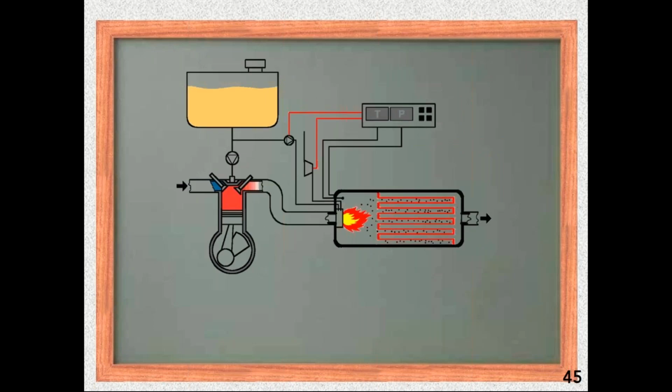And here you've got the hybrid system. So we've got a flame and we've got the red filter media. So that means there's catalyst there. So we use catalyst when it's available. We catalyze when there's enough heat to do so. But we also have the ability to bring in the flame for those times when temperatures in the duty cycle just do not generate the appropriate level of heat.